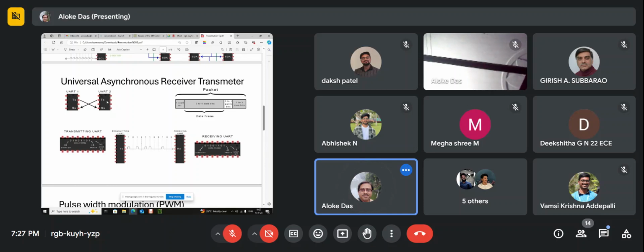So that has to be understood. Many things here are not evident through signals. Things like baud rate and parity bit all have to be known between the two devices. Then only you can configure it. So just keep this in mind.